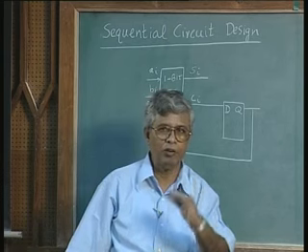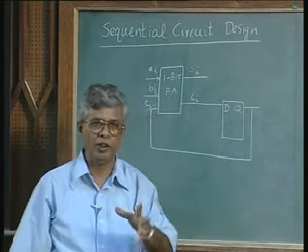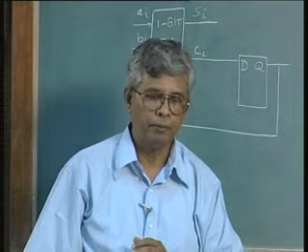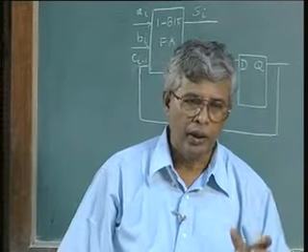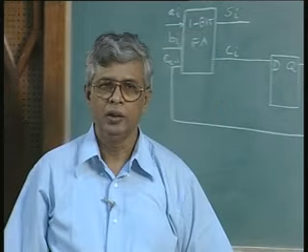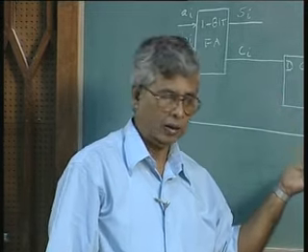Whereas in a combinational full adder, if you want to add a 4 bit number, we need 4 1 bit full adders, and if you want 8 bit addition, you need 8 1 bit full adders. So, we will have to tell in advance how many you need. Here I can use this repeatedly as long as I want.